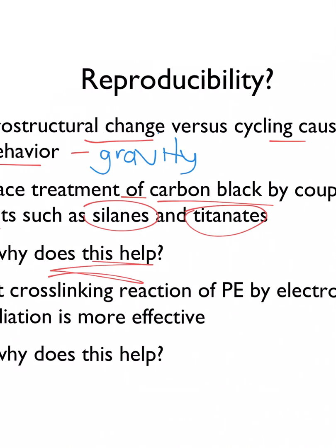Something else that is often used is a light cross-linking of the polyethylene by electron beams. And so this is actually pretty normal. All the wire that I talked about being made at miles per minute and coated with polymer typically goes through, well, I guess it can be electron beams, it can be gamma, a variety of radiation sources. After it leaves and is coated, it runs through a room that no one's allowed in and gets irradiated, and you cross-link all these coatings on this wire. All right. But in this context, we're only cross-linking it just a little bit.